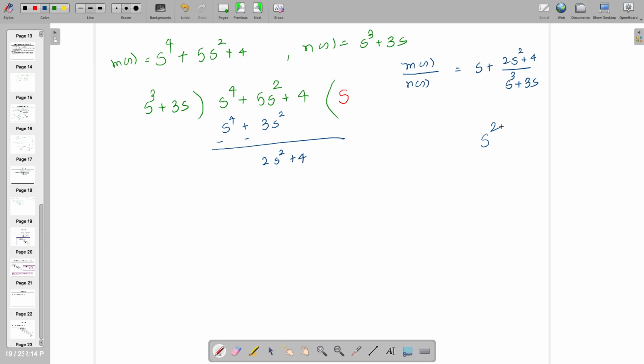I need to again divide it so that I'll get just the entry which will have only j omega axis entries, not two entries. So I'm again going to divide it, but when I'm going to divide it, I'm going to flip them. So this one will be divided with this entry. I'm taking this one here. When I'm dividing it, what am I going to get? s divided by 2, that is going to give me s cube plus 2s, so 2s.